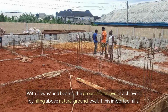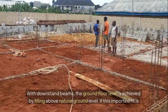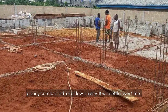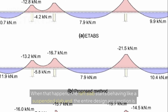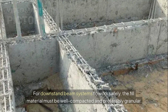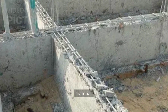With downstand beams, the ground floor level is achieved by filling above natural ground level. If this imported fill is poorly compacted, or of low quality, it will settle over time. When that happens, the raft slab starts behaving like a suspended slab, and the entire design assumption is compromised. For downstand beam systems to work safely, the fill material must be well compacted and preferably granular material.